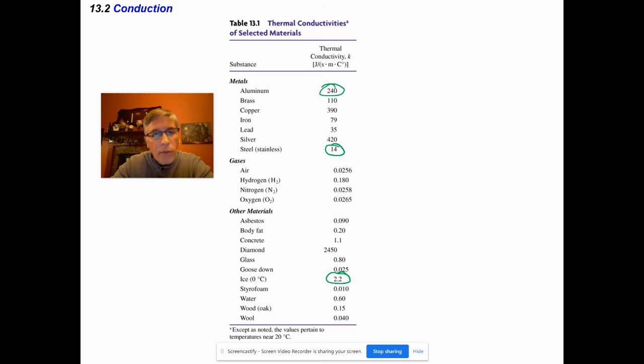You basically are more of a resistor than a thermal conductor. And so the more covering of ice you get, the harder it is for that heat to flow out. And that's what you don't want. You need that heat to flow so you can actually cool the insides because you have the refrigerant moving through there. So just a neat little concept to kind of look at as you're looking at these different thermal conductivities.